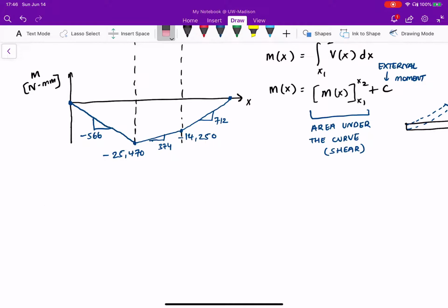And the way they've drawn it makes it easier to have z this way and x this way. You can do it the other way, but it doesn't matter. However you want to draw z, down or pointing upwards, the values for your moment diagram should be correct, negative or positive, because that tells you whether your shaft is in compression or at tension at that point.